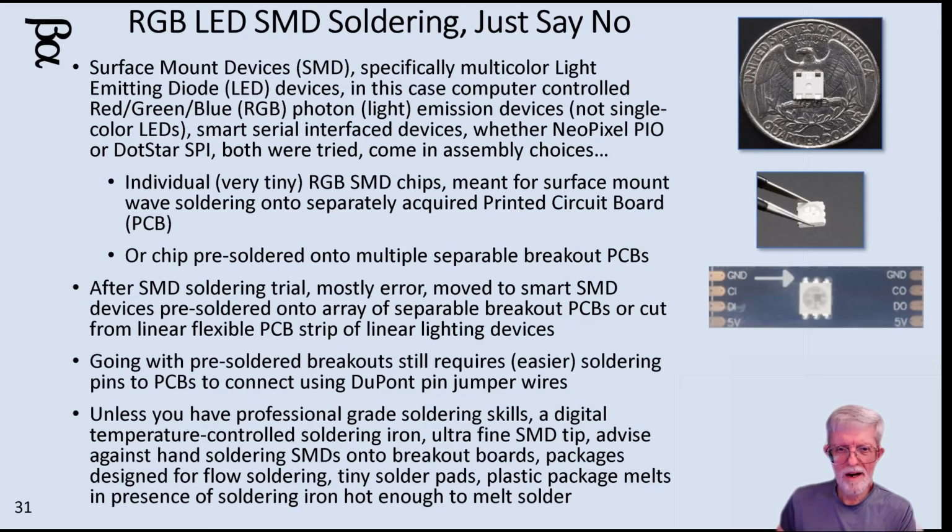And here's where I recommend do not buy the cheapest, just the raw parts, the surface mount devices, because you'll find that soldering them with ham-fisted humans and home soldering stations is no way to go. So don't buy the individual chips. See down at the bottom on the right, there's a long flexible strip that the LED chips are already surface mount soldered into, and I just took scissors and then attached leads via solder to the ends, which is much easier.